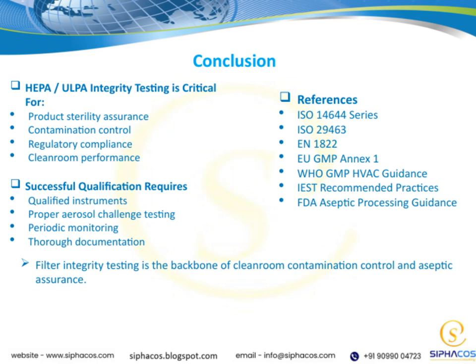Successful qualification of these filters depends on a few key elements. First, using qualified instruments, meaning they're properly calibrated and validated, is essential. Second, conducting the proper aerosol challenge testing allows us to assess the filter's integrity accurately. Third, periodic monitoring is vital to catch any degradation over time.